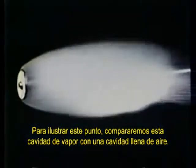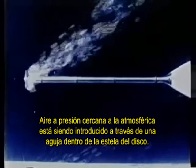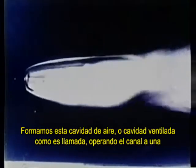To illustrate this point, we will compare this vapor cavity with an air-filled cavity. Air at near atmospheric pressure is being introduced through the sting into the wake of the disk. Its envelope looks very much like the vapor cavity we have just seen. We formed this air cavity, or ventilated cavity as it is called, by operating the channel at a low water speed and high ambient pressure. To form the vapor cavity, the channel was operated at a much higher speed and under considerably lower pressure to obtain approximately the same cavitation number.